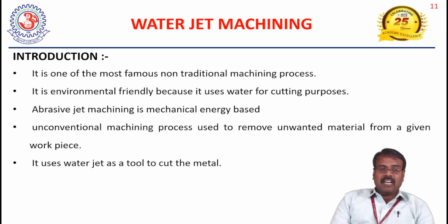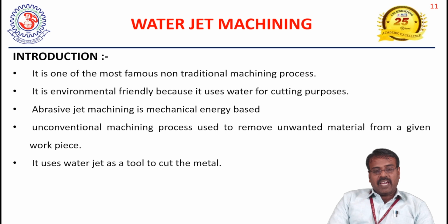It is eco-friendly or environmentally friendly because it uses water for the cutting process, with no other side effects. Abrasive jet machining is a mechanical-based one, because whenever you are using hard materials, at that time we add abrasives along with the water, so that it helps us to remove the material effectively.